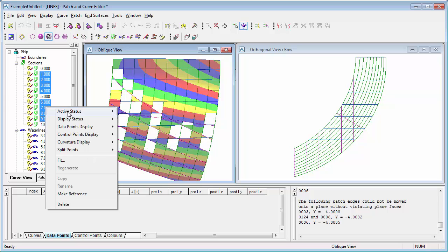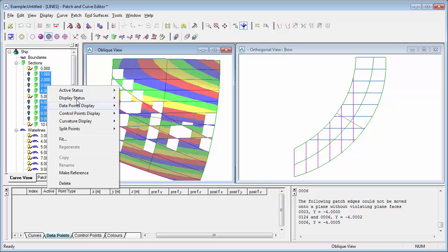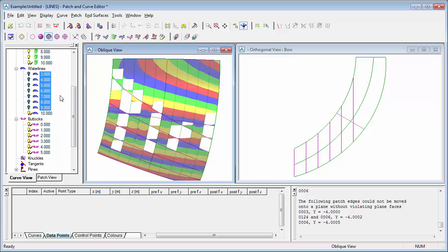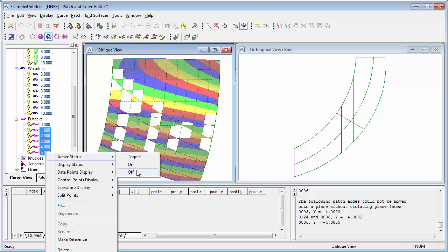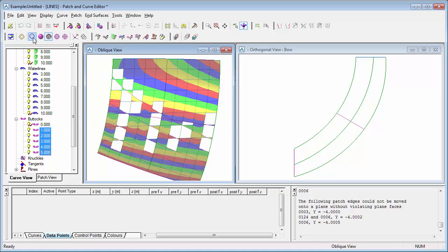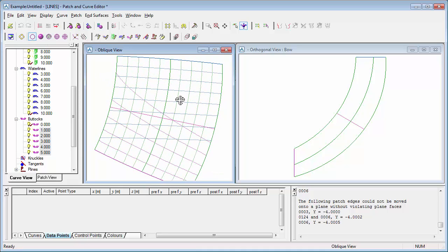We're going to turn off these additional curves, have them displayed only as dotted lines, and the system will use them to fit the internal shape of the patch using the existing curve network that we created at the start of this session. So the original curve network and the dotted lines are the new curves.